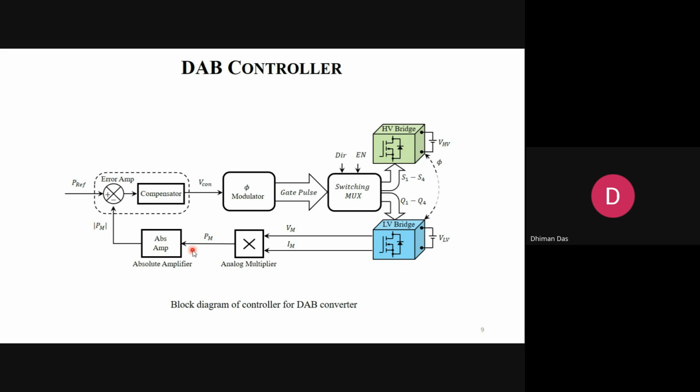If you drop 1 volt across the diode, you cannot allow that drop, because your controller will see some offset. So to avoid that, we need to implement an absolute value amplifier, which is an active rectification.